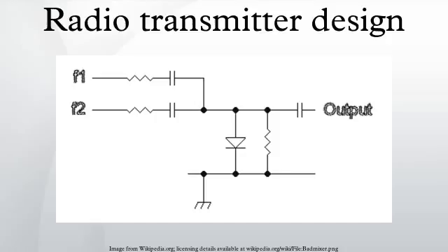AM-related modes. Several derivatives of AM are in common use. These are single sideband modulation, SSB, or SSB-AM. Single sideband full carrier modulation is very similar to single sideband suppressed carrier modulation. It is used where it is necessary to receive the audio on an AM receiver, while using less bandwidth than with double sideband AM. Due to high distortion, it is seldom used.